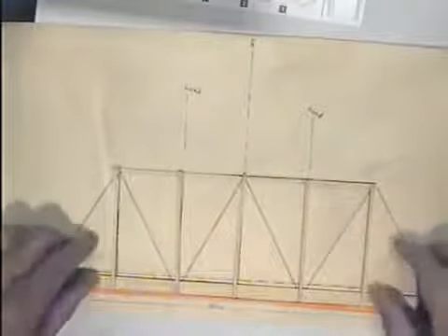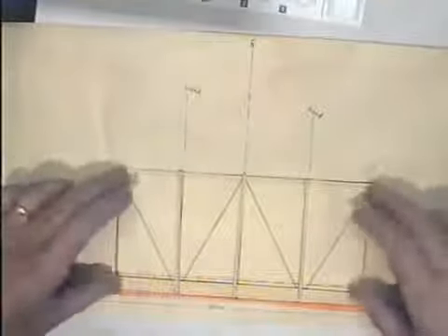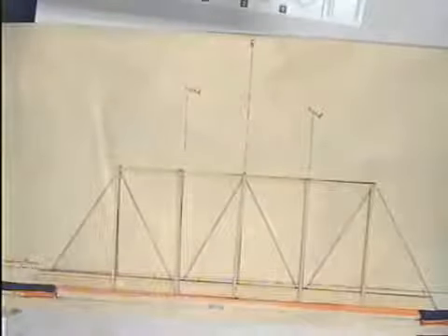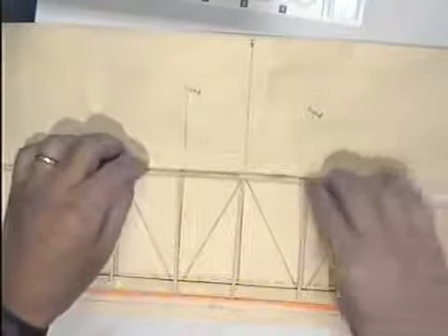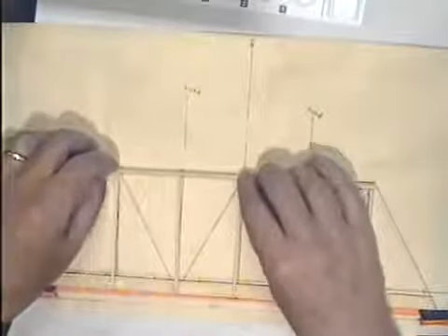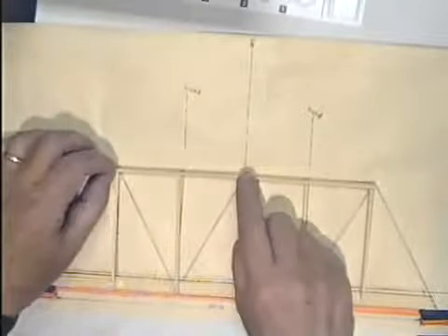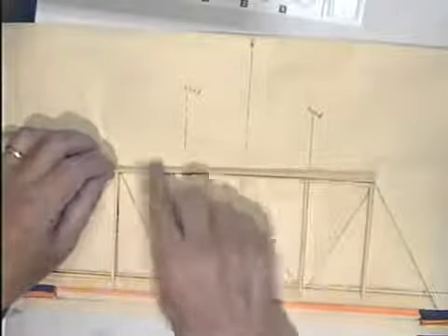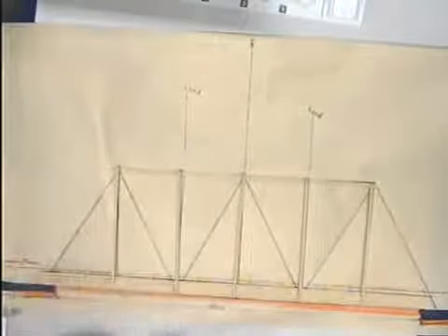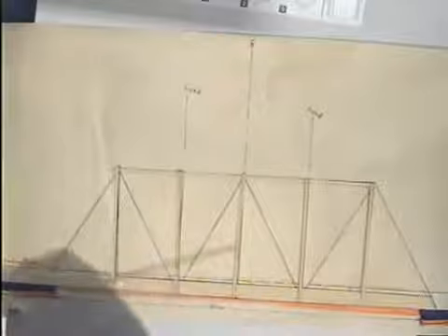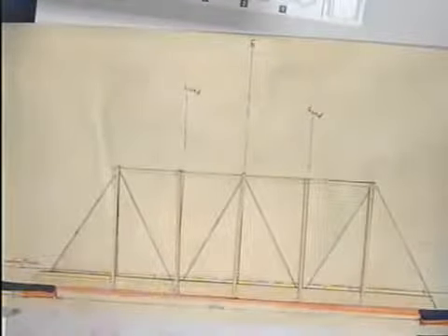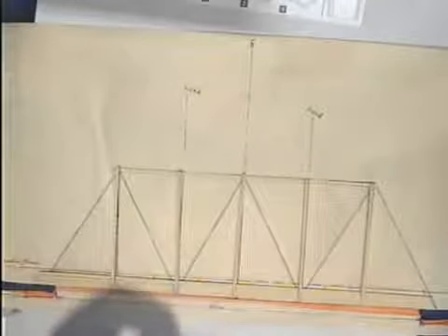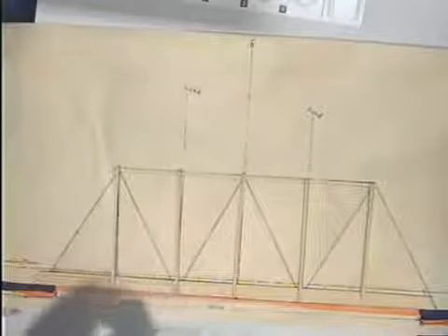Build a piece of the bridge. Okay. Take and, if you're building it like that, and then you want to attach another piece here, use straight pins or something to hold it in place. And then, if you're using lap joints, like I would here with just one piece on top of the other, just take and break it with your finger. If you want to cut it, use a single edge razor blade or a Zona saw. Emphasize single edge razor blade.